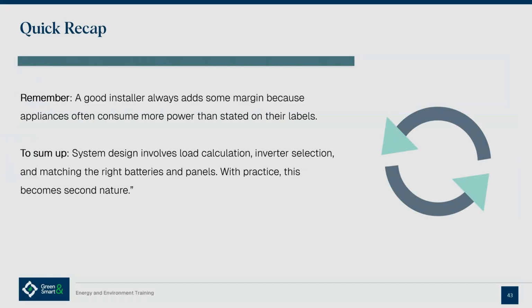Remember, a good installer always adds some margin because appliances often consume more power than stated on their labels. To sum up, system design involves load calculation, inverter selection, and matching the right batteries and panels. With practice, this becomes second nature.